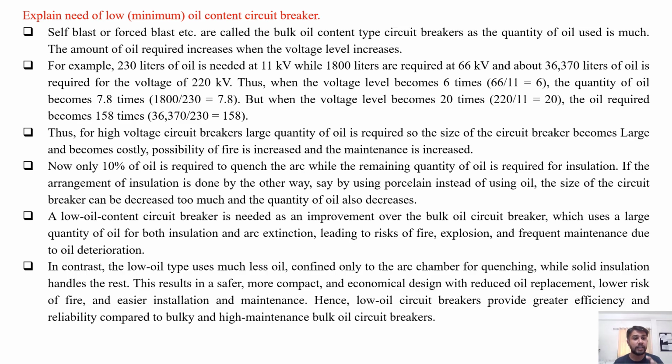The size of the circuit breaker can be decreased too much and the quantity of the oil also decreases. A low oil content circuit breaker is needed as an improvement over the bulk oil circuit breaker, which uses a large quantity of oil for both insulation as well as arc extinction purposes, leading to the risk of fire, explosion and frequent maintenance due to oil deterioration.